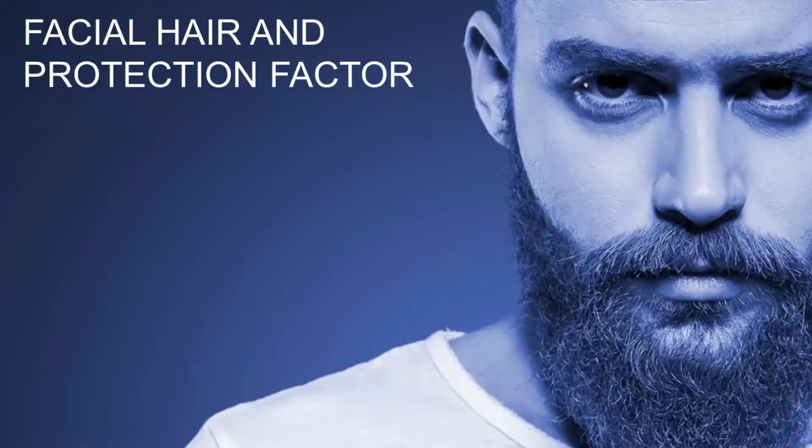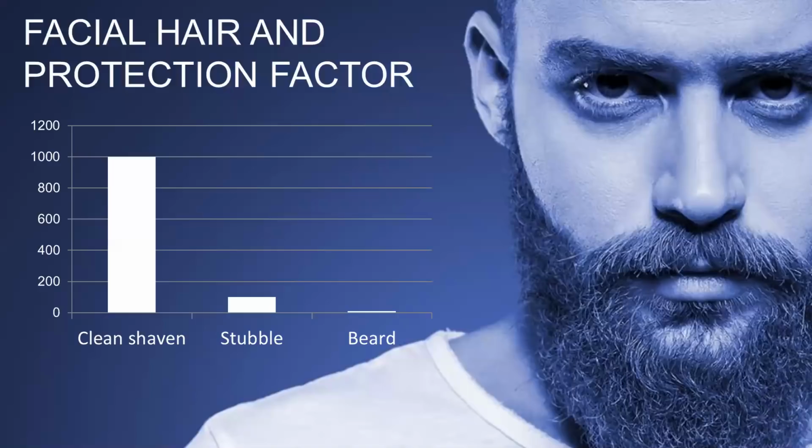Facial hair. Now, we could spend days and weeks on this, and I'm sure you have, all of you individually. The reality, if you're clean shaven, a mask will give you a level of protection. It doesn't matter what that level is, but it will give you a level of protection based upon the fact that the mask is sealing to your face. If you have stubble in the area where the mask seals, and that's the key thing, where the mask seals, you will lose 90% of the protection that mask provides you. You'll only get 10% of what you're expecting to achieve.